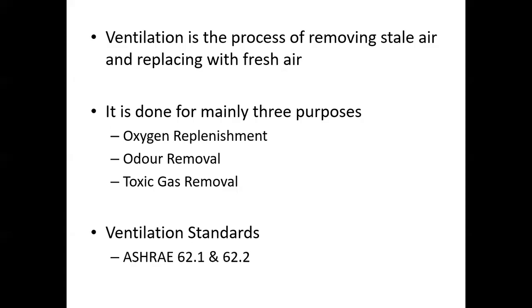These are the considerations that come inside the negative ventilation aspect itself. So for negative ventilation, how to calculate the fresh air CFM? For this one, there is only one method that we will be following. It's the ACPH method. That means you know the equation, ACPH into volume divided by 60. So how did we get these ACPH values? While doing some projects, you've been seeing some sort of value consideration, like consider one ACPH FA, consider one ACPH fresh air, isn't it?